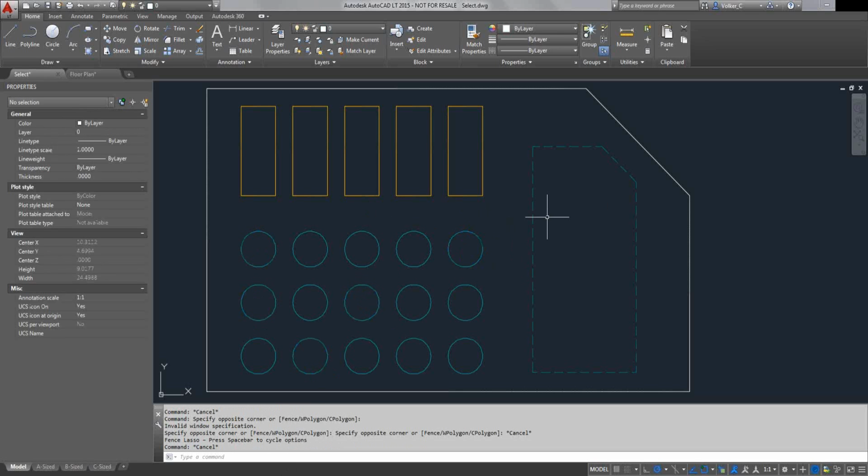So I was going to mention, for a lot of folks, they're not sure what that is, and that is what that is. It can be turned off in the options dialog box on the selection tab. There is an option to turn off that lasso. So if it's something that you're just not used to or don't find particularly helpful, that can be turned off. But just a note there, because we've had a lot of questions around what exactly that is and why am I getting that instead of the standard rectangle. Right, yeah, and we will go into the options dialog, and I'll be showing you where you can change the default settings for this. So thanks for bringing that up, Sean.